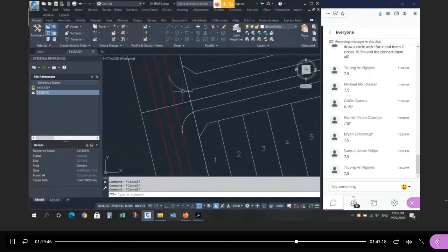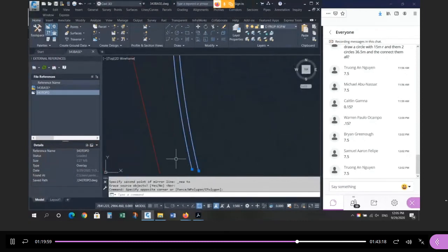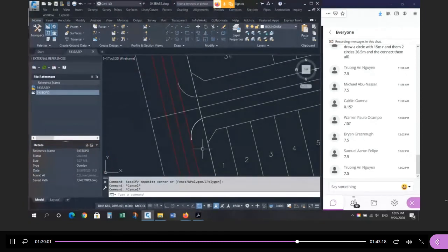Okay. The other thing you want to be mindful of is make sure you draw each fillet separately, right? If I mirror this thing from center to center, if I mirror it on the center line, it's not the same. Why? Because the line I used for filleting here and the line I used for filleting here are not parallel.